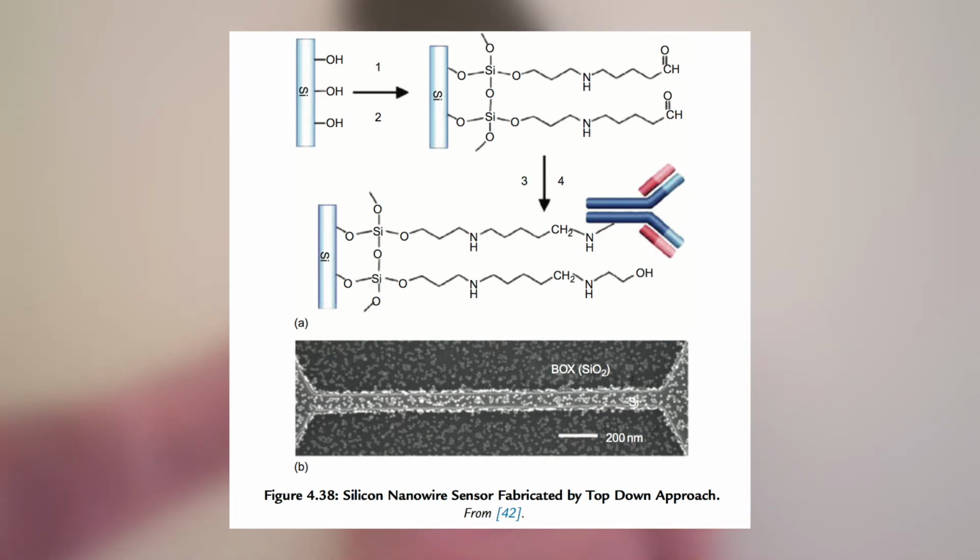With this sensor, the nanowire is connected to two electrodes which measure the conductance. In one of the applications, the nanowire can be modified to undergo protonation and deprotonation of a specific molecule or protein. This change in the surface charge allows the FET to detect the change in pH. This allows conductance and pH measurements to be made using the sensor.